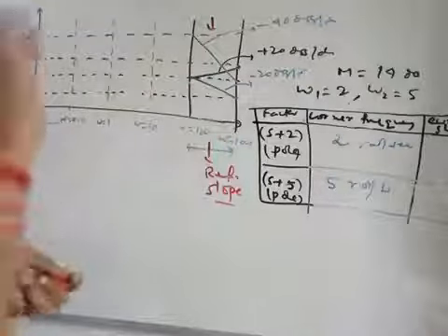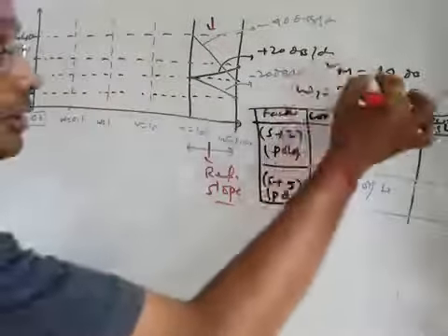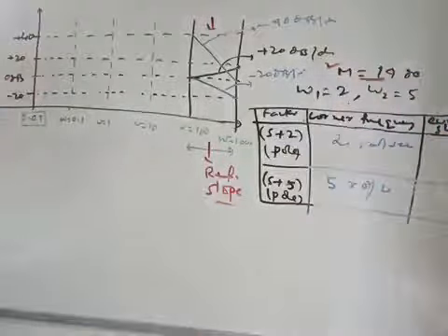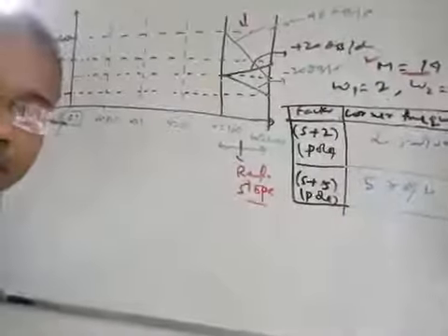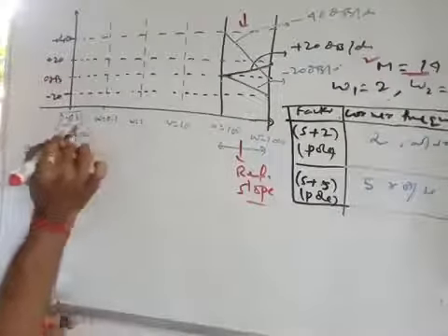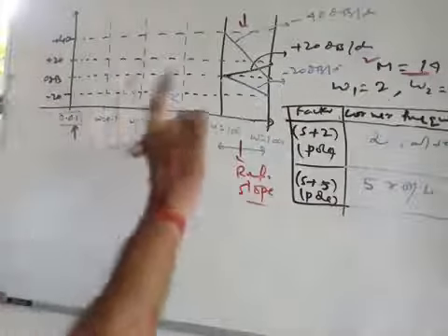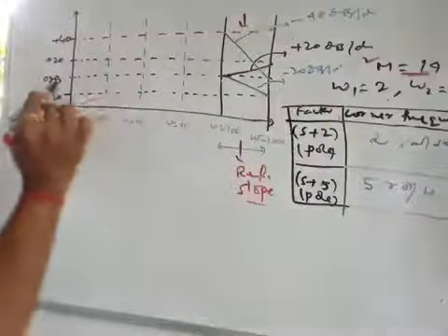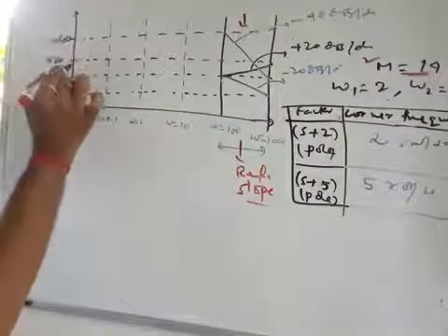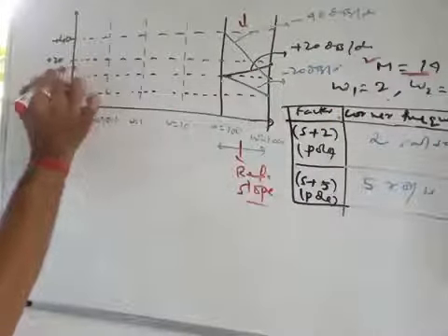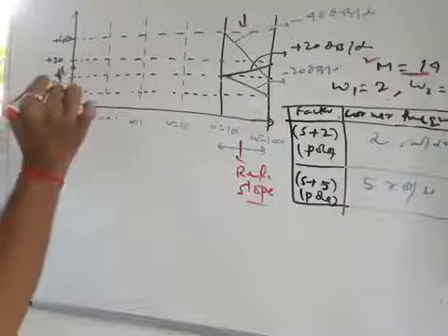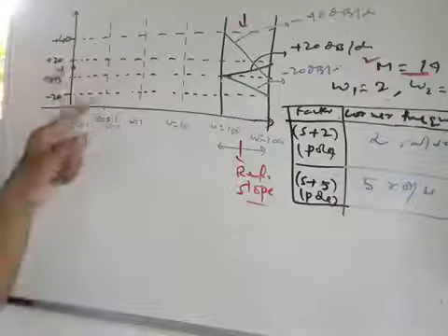Next, start with this magnitude. What is the magnitude? It is 14 dB, the magnitude at omega equal to 0.01. So at this frequency the magnitude is calculated, and the calculation steps are shown. So this is 14 dB. You can say this is your 14 dB, right? So this is your starting value of the magnitude.